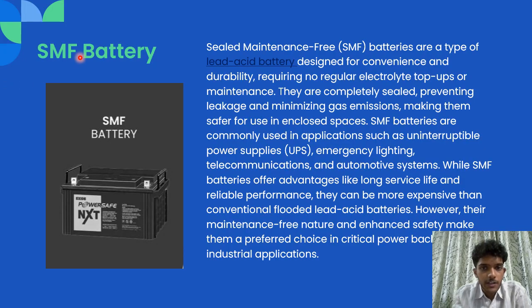Now we move on to a variation of the lead acid battery, which is the SMF battery. As previously mentioned, in the lead acid battery, SMF batteries are a type of lead acid batteries designed for convenience and durability, requiring no regular electrolyte top-ups or maintenance. This is because this battery is completely sealed from the outside. Therefore, it requires no top-up, whereas in lead acid batteries, you need to keep topping up distilled water to enable the reaction to keep going on.